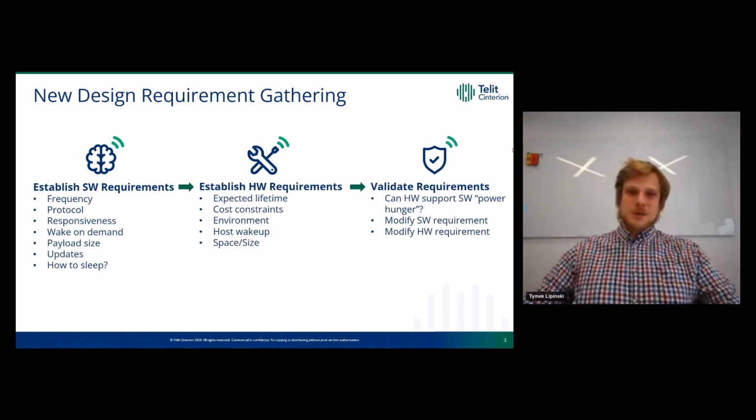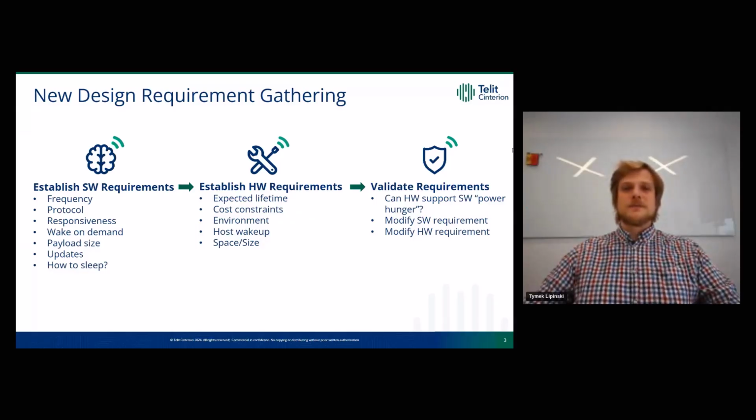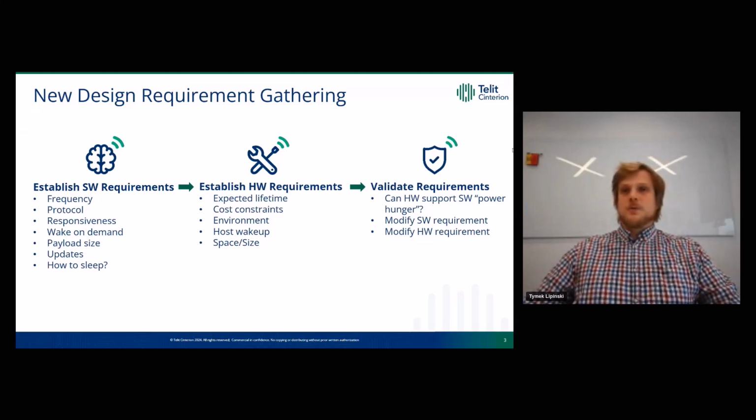Once we are ready with our software requirements and a general idea about our project, we have to establish some hardware requirements. What will be the expected lifetime of the device? Factor in the battery life. What is our cost constraint? How much money can we spend on the hardware? Is it going to be a low-cost device or a high-cost device? What kind of environment will the device be deployed in? So mainly temperature, humidity, vibration. What are our options for host wake-up? We have to wake up our host, of course, to do something periodically. And most importantly, what is our space and size constraint for our hardware?